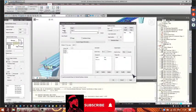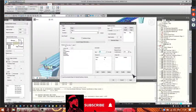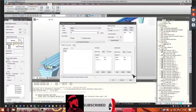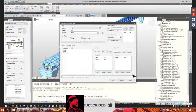In stage 1, we can activate the slab as an element, and we can deactivate the loads of group 1, activating instead the loads relative to the sidewalk on the last day, in this case. Finally, in stage 2, we set a duration of 100 years to see the effect of long terms. And in addition, we apply the weight of the group 2 loads.